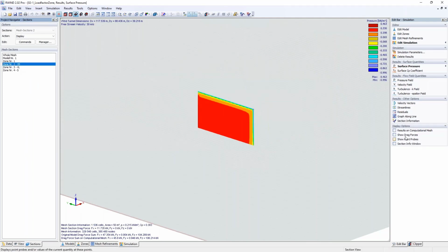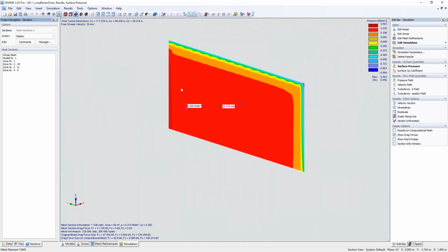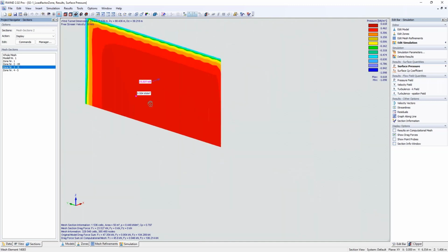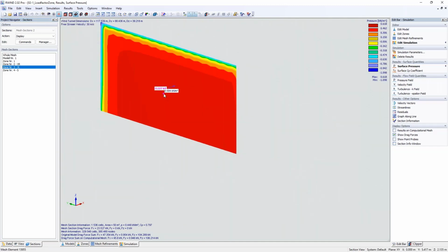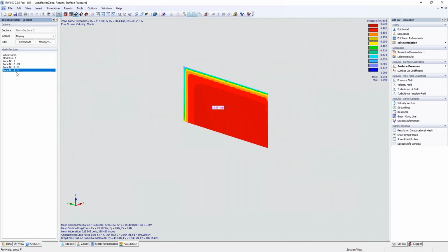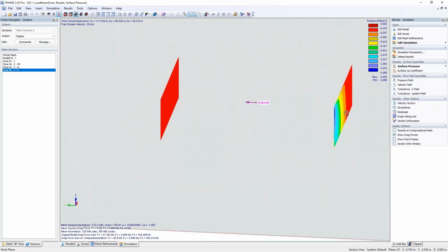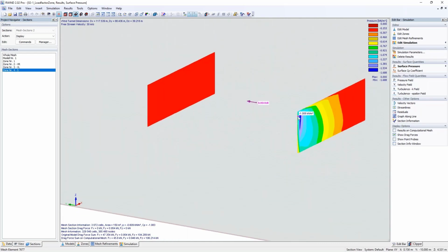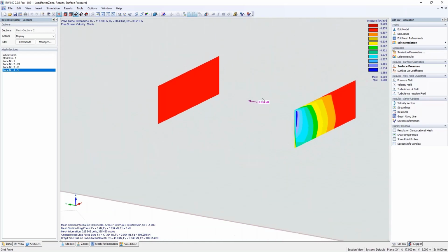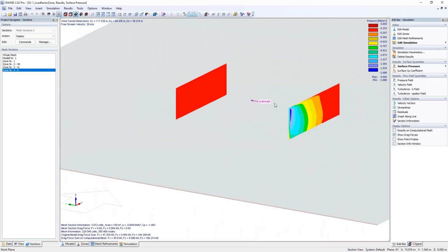So hitting on the right zone and showing the drag force, you can see that this area is gathering roughly 11 kilonewton. And if you hit onto the left zone, it's 20.3 or 23 kilonewton. So it's doubled because we reduced the right side by a half. And you could, of course, also evaluate the sides. But this was just an example that you can also adjust multiple zones.